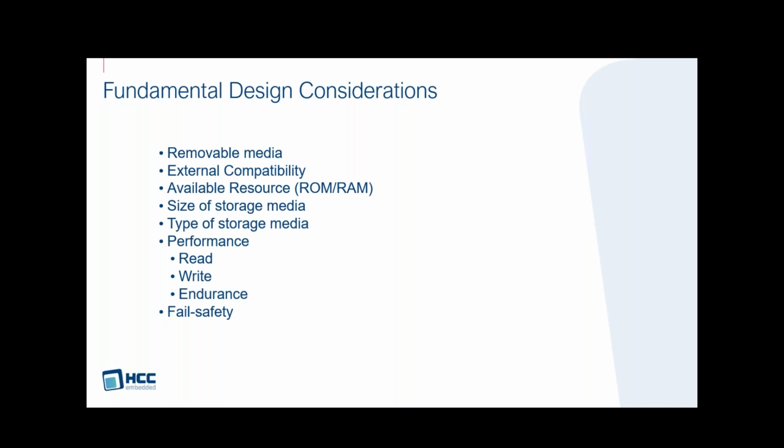I mean, in general, the largest is an SSD these days, but it's not really suitable for an embedded system. So typically, you want to try and find the right balance between your data requirements and an easy, convenient way to manage the media. The type of storage media relates back to the size, relates back to the removability of it, and relates back to the interfaces.